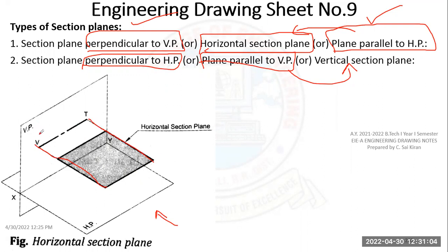We already learned how to draw the section line. So first line, dot, line, and this should be darker, and again this is lighter. Till here it is lighter, and again from here it should be darker. These two things will be darker. And here we have to write VT because it is on the vertical plane.